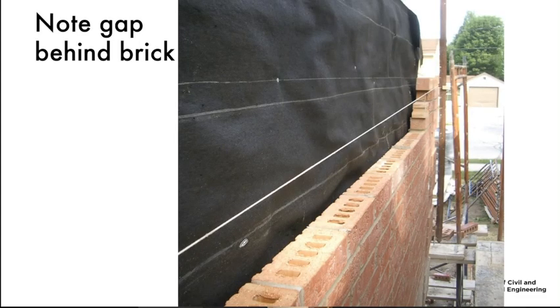So in the good old days, this was the water-resistant barrier. We would use felt paper installed in shingle fashion, and felt paper is made of short, coarse fibers. Then they are run through a bath of asphalt, and the asphalt absorbs into the fibers, but there are gaps between the fibers, microscopic gaps that allow water vapor to pass through, but the asphalt coating protects the felt, which is a paper-based product, from rapid decay, and it also renders the surface highly water repellent.